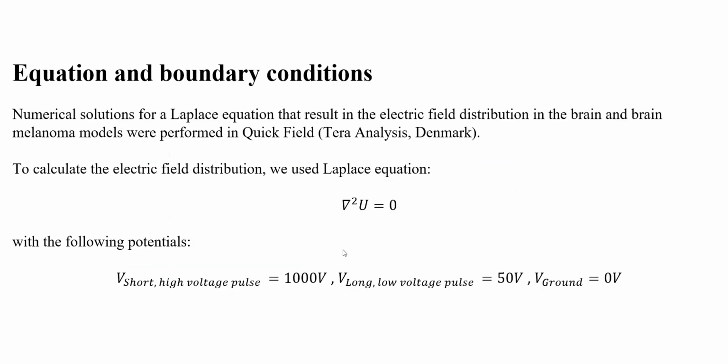To model the distribution of the electric field in the brain and melanoma tumor during E-biopsy, we use the finite element method, which allows us to find an approximate solution in complex geometries. We solve the Laplace equation with boundary conditions defined by the applied voltage. So first a short high voltage pulse, followed by a long low voltage pulse.